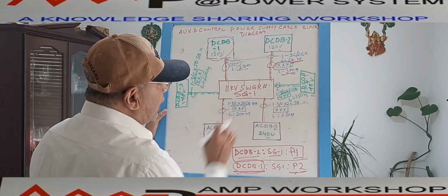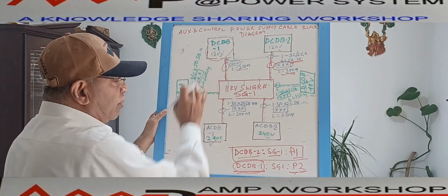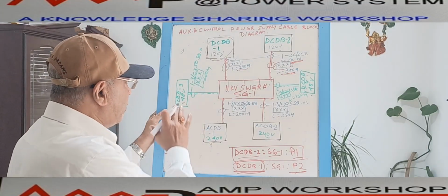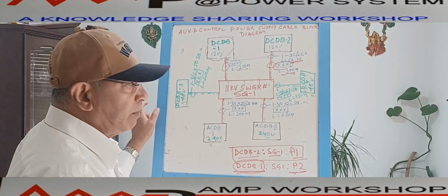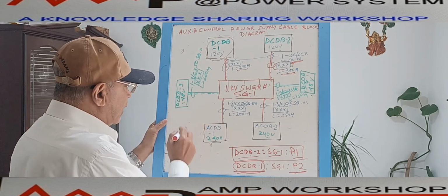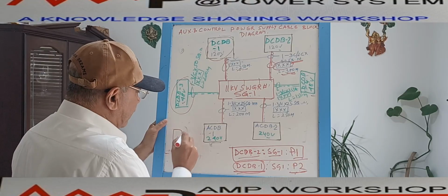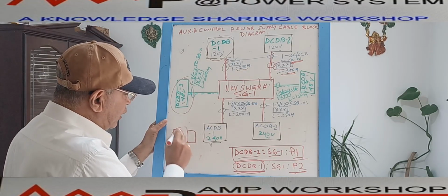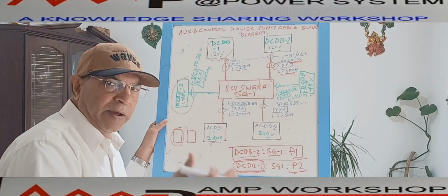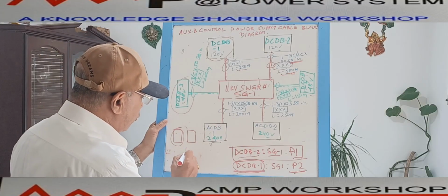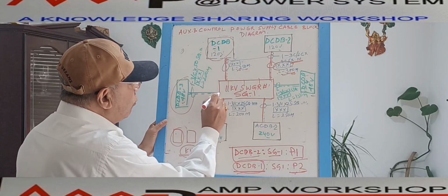Similarly for the 48 volt DC, this is more critical because the voltage is very low. The cable has to be calculated very precisely based on the various loads. We calculate how much VA load the 48 volt DC has for each panel, because this supply will cater to, suppose this switchgear has 25 panels, all the 25 panels' power requirement. We sum up all 25 panels and, based on that, calculate the total kVA requirement, and from it the full load current.